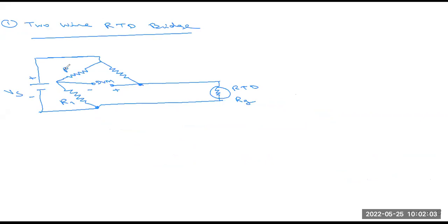This is R1, R2 and R3. So this is the basic difference between the 2-wire and 3-wire. This R3 is directly connected to the DVM and to the RTD terminal. But when we use 3-wire RTD, the resistance R3 is another difference in connections we have to attach here. So this R3 does not change any DVM, that is digital voltmeter, voltage. So this is the basic difference between the 2-wire and 3-wire.